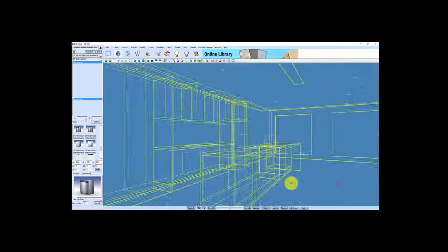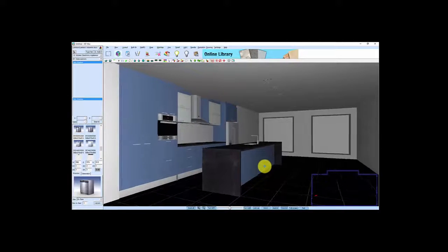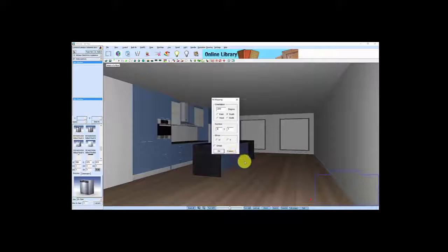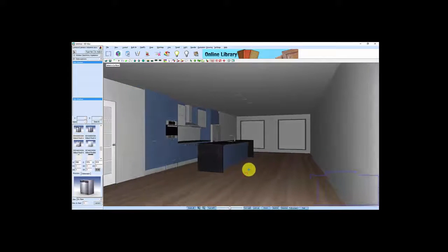From there, what we'll do is start adding smaller accessories. So go in and change the floor. I can click on the floor. I'm going to change the floor to a timber material. So go from carpet to solid timber. I'm going to use Tasmanian oak. We go OK. Alright, I just need to render that. So we go to render, fit map, select, right click. I want to change it so the direction of the grain is running along the wall, and I just have to change the different laminations. So that's 3, we'll just go 1.5. So now that looks like real timber.